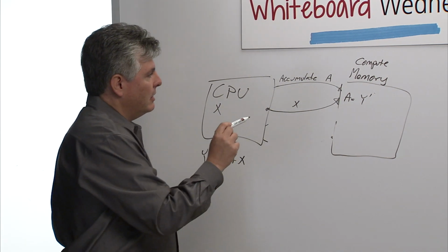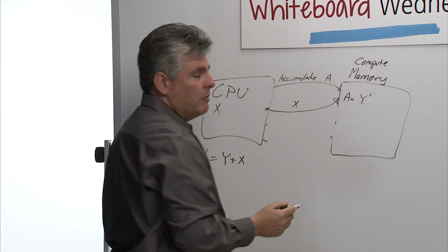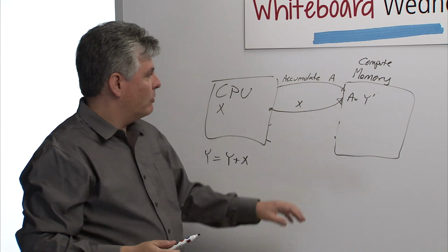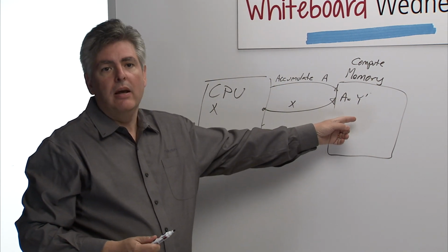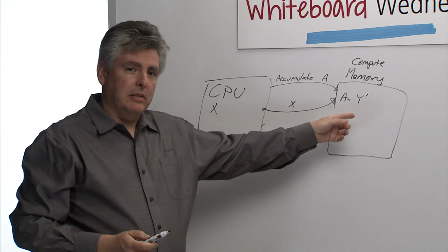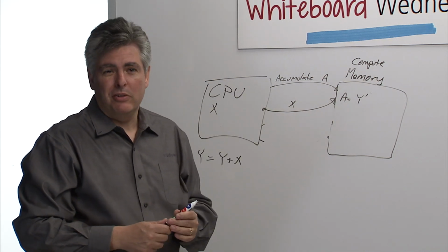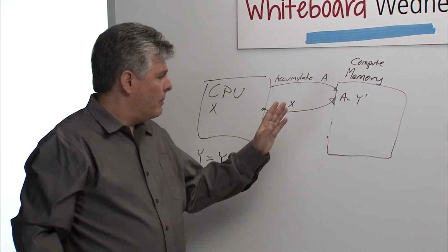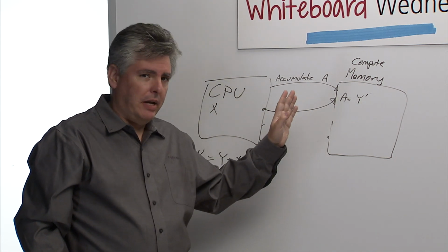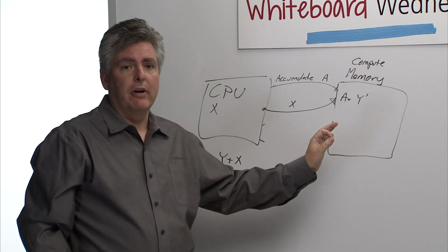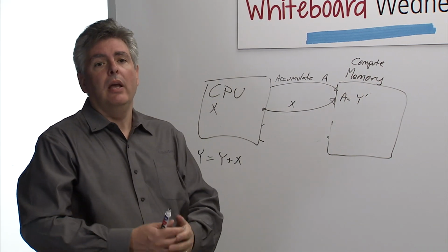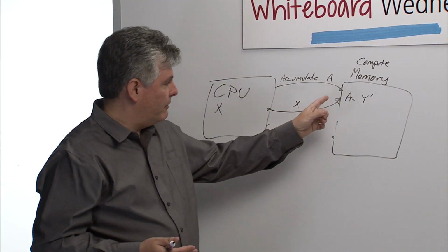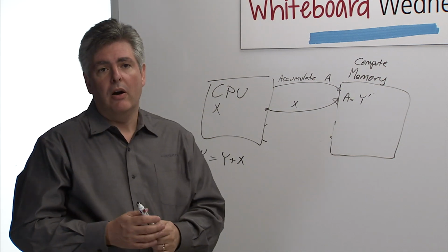So the first thing is the memory dies themselves are really, really bad at doing logic functions. They're optimized for one thing. On a typical memory chip today, I'm going to put down 4 billion or 8 billion transistors. I'm going to sell that for $4 or $8 if I'm a memory vendor, something like that approximately. So that process is really, really optimized for doing that one function, which is the memory function. When you start trying to put logic in here, it doesn't really function very well. The area is quite large, and the cost of putting those simple logic functions into this memory is quite high.